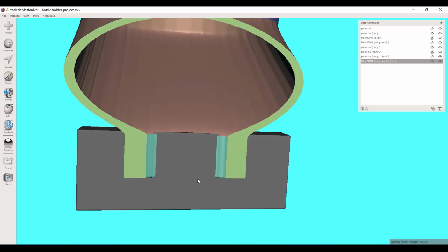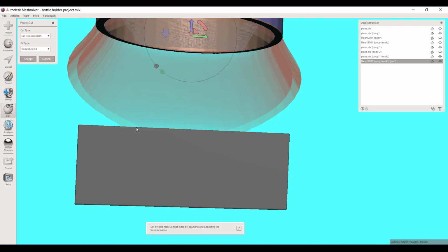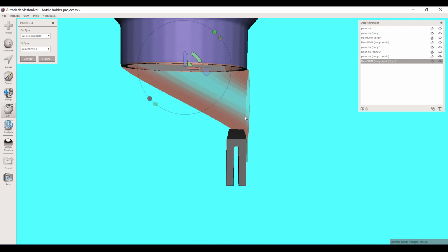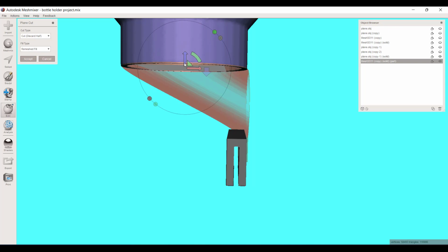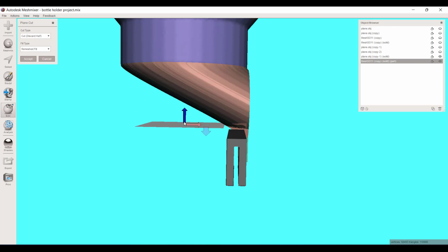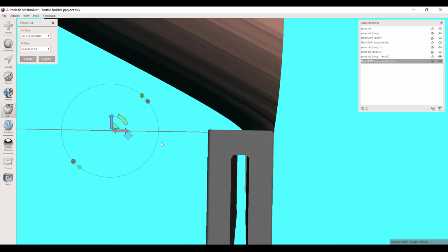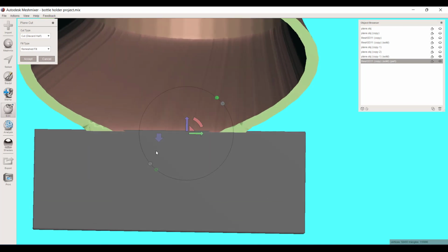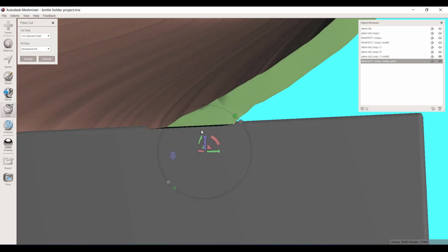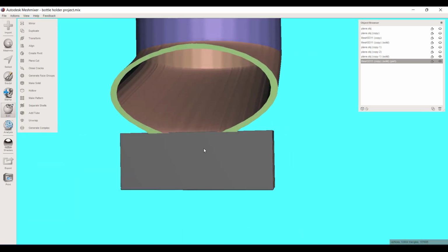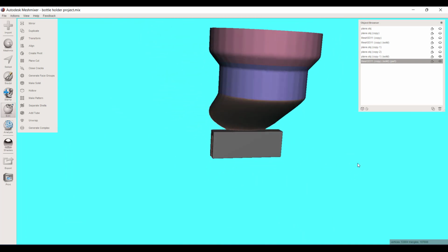All right. I also don't need any of this portion. So let's go to Edit, Plane Cut. Now this one, I don't care if it cuts indefinitely through it. So I'm going to, oops, let's undo that. This is in the right dimension. I just need to pull it down. So I'm looking at it. And again, don't have to be precise. I actually do want it to go just a little bit beyond that edge. So I'm going to accept that. All right, now you have a nice funnel shape.